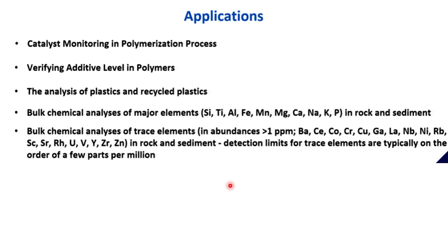That can also be done through X-ray. For verifying additive level in polymer, there are different zinc or phosphorus based additives used in polymers, and how much is present in your composite material, you can determine quantitatively through XRF study.